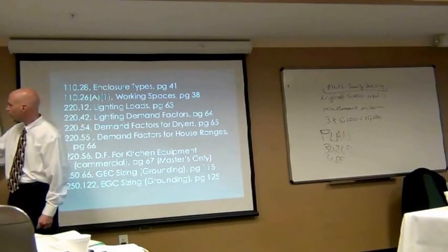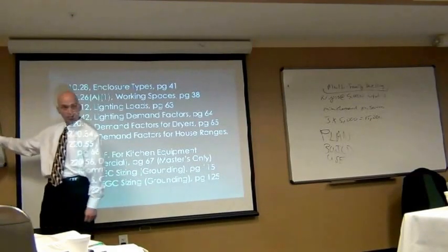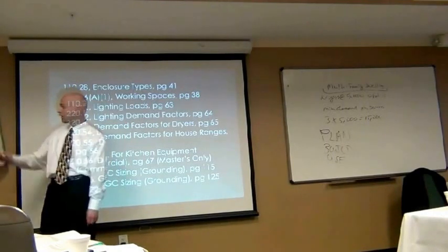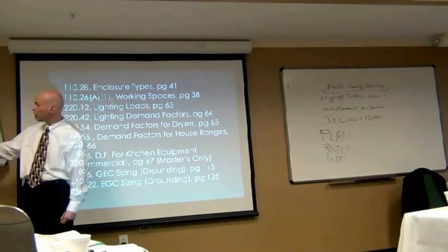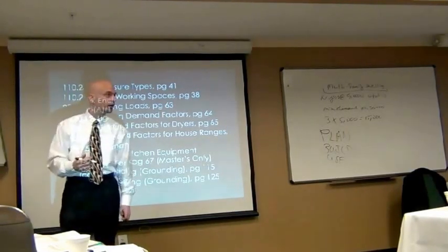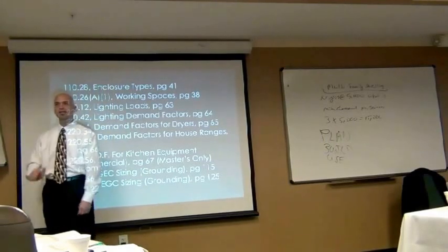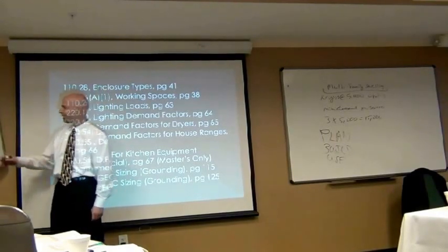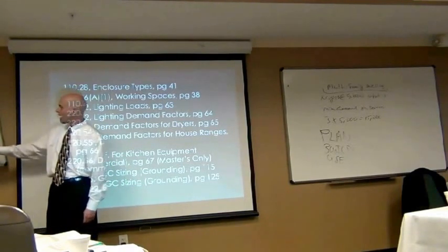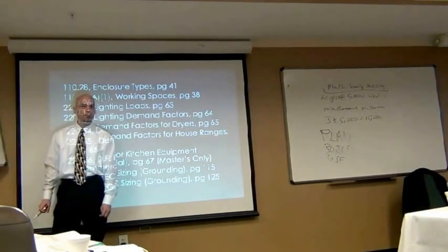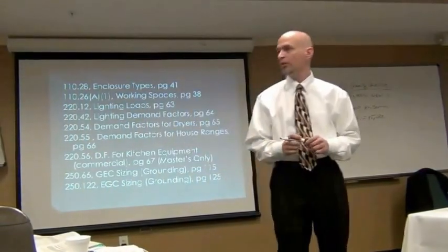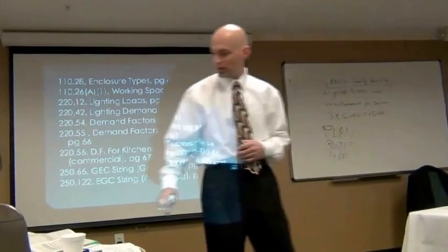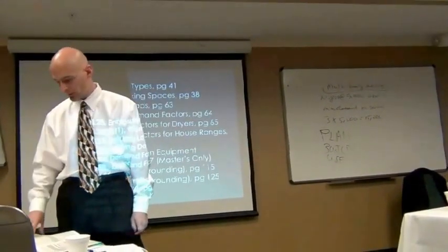So if I normally put a number 8 at 50, but what I've got in there is obviously number 6, so I know they increase those on this one right here, and especially these right here, to compensate for voltage drop. I have at least 1 step larger on my equipment grounding conductor under note B, right? So I have increased it from number 10. I'd actually have to put that at a number, what? What size ground electrical conductor would I have to have if I had to increase the phase conductors by 1 step? Number 8, right? So you basically would increase this table value by the same number of steps.